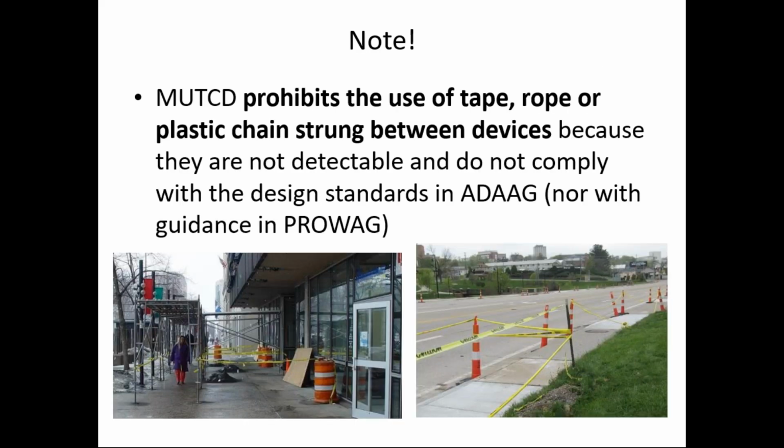But before we do that, I want to mention that we should not be using tape or rope or plastic chain strung between various devices. They're simply not detectable, and they do not comply with ADAAG or PROWAG. But yet, as I noted, you see this around the country quite a bit. These are not appropriate devices.